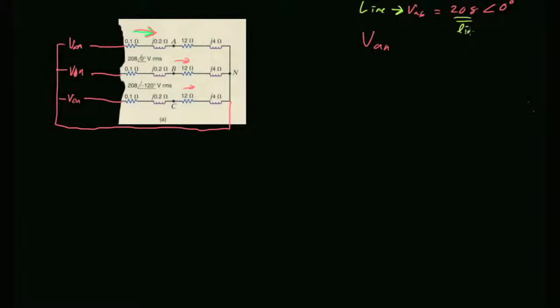And essentially what I'm asking you for is a phase voltage, the voltage between the A phase and ground. And there was a conversion for that, was there not? We said that the line voltage always equaled the phase voltage times √3 with an extra 30 degrees of phase. So now I want to work this backwards. By using a delta configuration, they're giving you the line voltage, and in order to do the easy solution, you need to get the phase voltage back. So the phase voltage is V_L over √3.